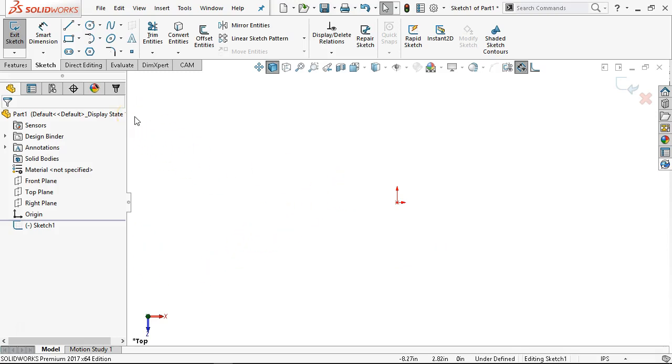All right, so our most common element is going to be the line or the arc circle. Out of that group, probably the line. If it's a cylindrical shape, if it has some additional geometry in it, there's a crossover where I have to make a decision: if this is purely cylindrical, at what point do I do a revolve as opposed to an extrude? Well, that's a discussion for the features, but it is going to drive some of my decision tree to generate these sketches and get it started.